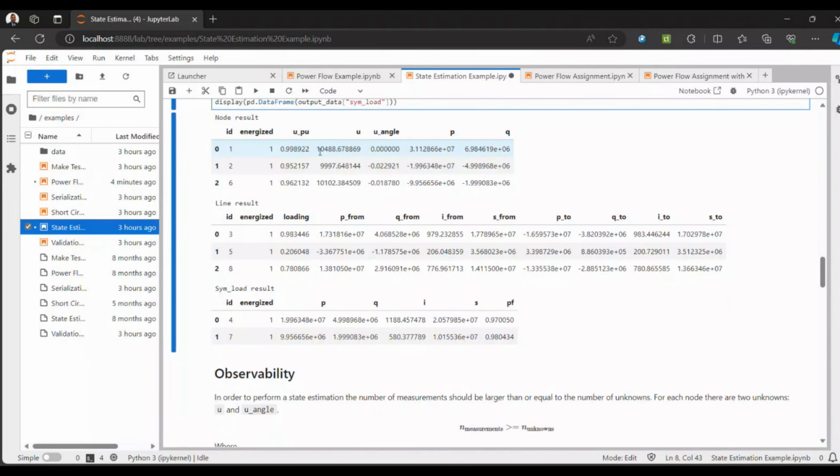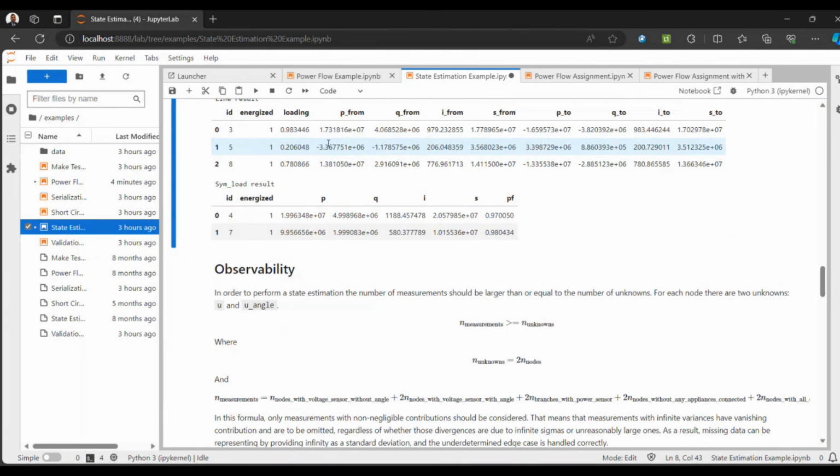in a similar way as power flow. One thing to note in state estimation is that sometimes you might get another error called sparse matrix error, and that usually comes in when you don't provide enough measurements for the grid that you're trying to estimate. So as a really rough calculation, you can realize that you at least need more measurements than the number of unknown variables that are present. It also depends on where these sensors are located, by the way. But this is a really rough way to calculate if you have enough measurements or not. The location matters as well.